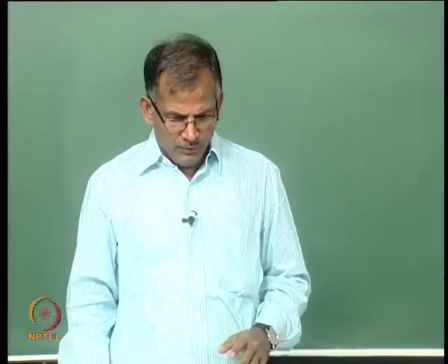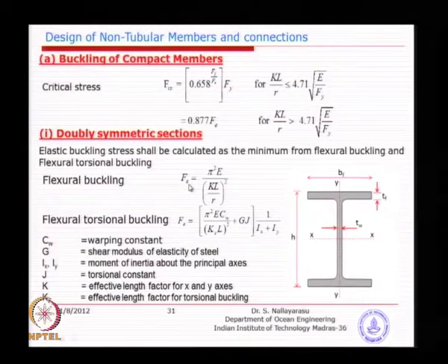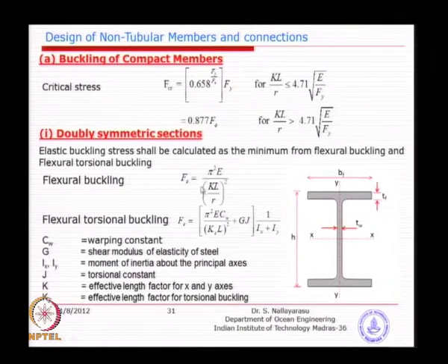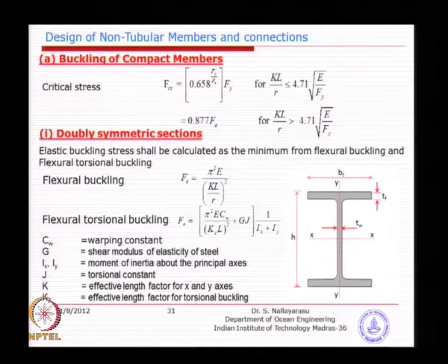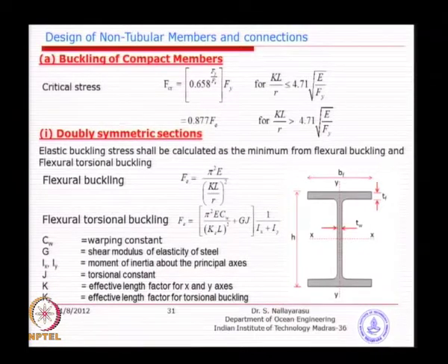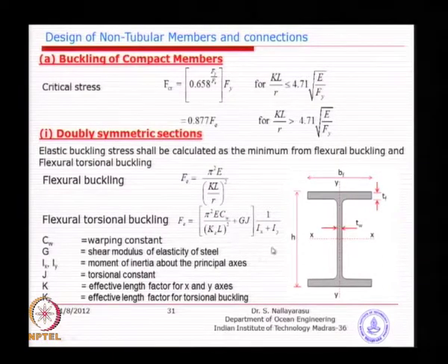This means even before a global buckling occurs, because global buckling is because of slenderness, which is basically the KL by r value, where K and L represent the length of the member and r represents the radius of gyration, which corresponds to the section. So, KL by r will be a global buckling phenomenon, whereas the flexural torsional buckling is almost a mixed condition, basically global as well as the local flange effects are going to affect it. The larger the flange, the earlier it is going to fail. So, that formula is also an empirical formula.